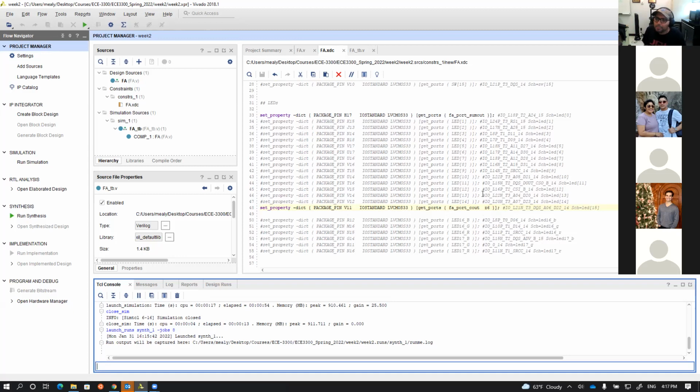You know why? Because if you keep trying and running synthesis, and keep trying and running synthesis, what will happen? You will be tired, and it will take too much time. So a test bench can tell you early what the problem is, and then you can fix it before running synthesis. As you can see, it's taking forever, right? But the consequence on the board itself, no, there shouldn't be. You already have a protection.